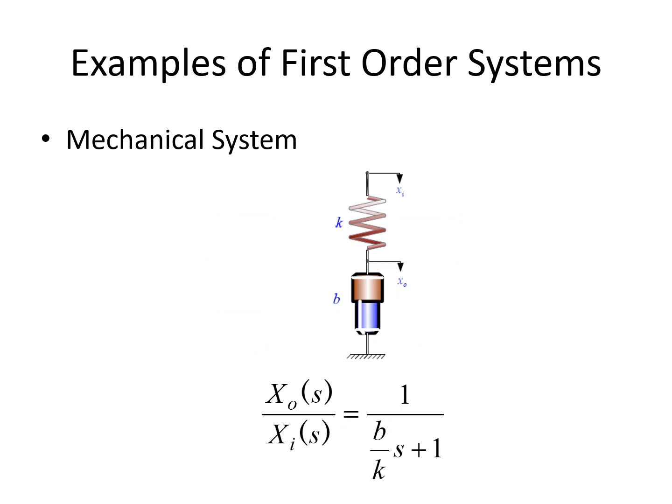And this is an example of a mechanical system with the spring and a dashpot, which is given as 1 divided by (B/K)s plus 1. So this is taken as your T and this is taken as your K. Time constant here is B by K.